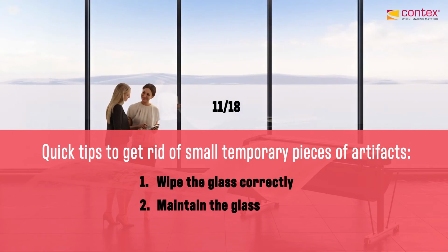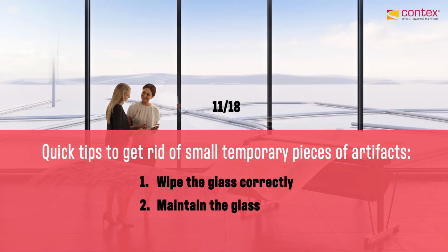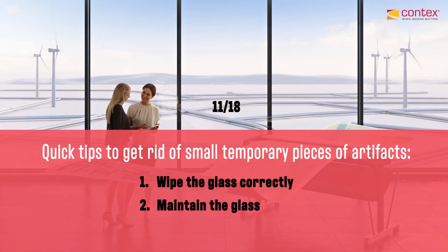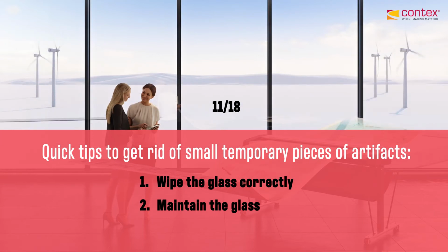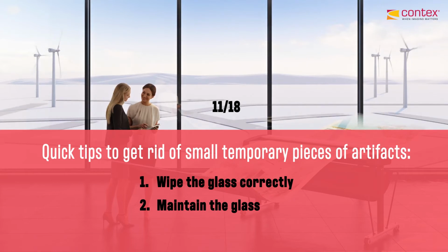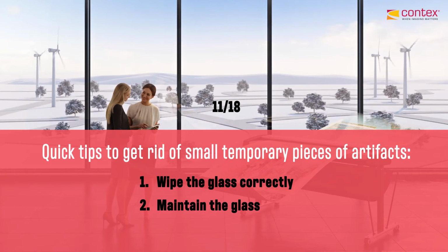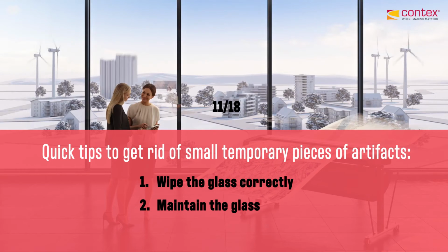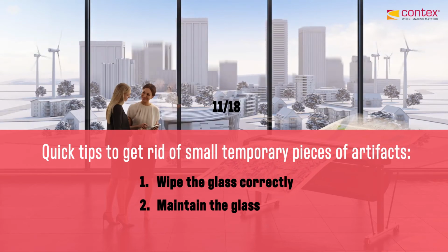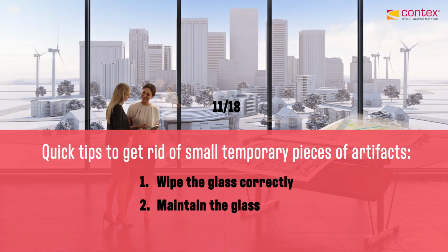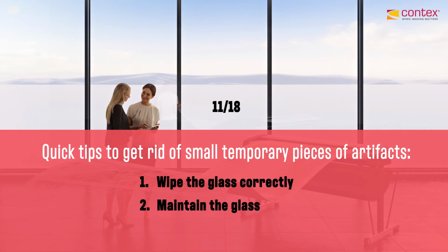The advantage of this is it's kind of a waxy surface that fills in all of the pores. And the idea is, if a grit particle, which is almost certainly going to be in existence, it keeps it traveling through the scanner so it doesn't show up as a streak. The idea is to keep the grit particles moving through and across the glass and not sticking to the glass. And that will go a long, long ways.